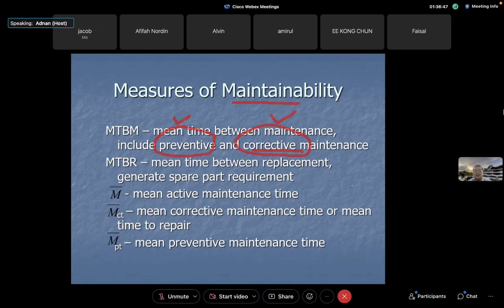So if you're in charge of a traffic light, change the bulb regularly, as recommended by the manufacturer. The manufacturer recommends how long the bulb should be used before changing. Every 1 year, or maybe every 6 months, depending on the product. Also for a heavy-traffic road, you need to change it according to a preventive maintenance schedule. Basically, changing street light bulbs on the road should be scheduled maintenance, because if we wait until failure, it's going to be expensive to change the bulbs one by one, only when they fail.